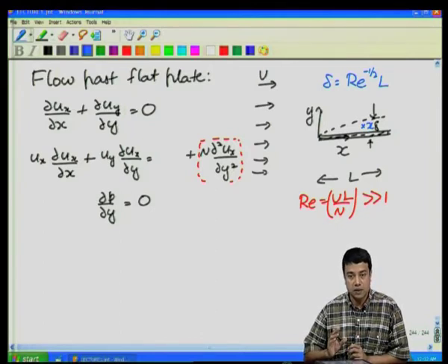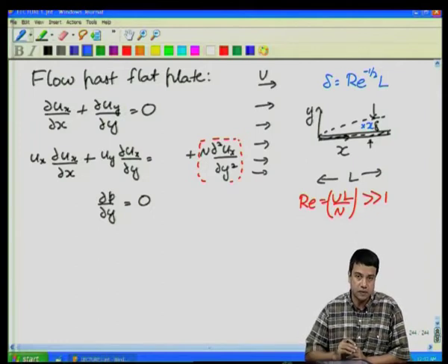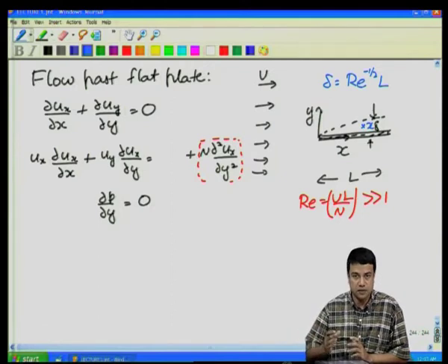It will only depend upon the distance to the upstream edge, because it is only downstream convection that is affecting the dynamics of the flow as well as perpendicular diffusion. Since L is no longer a relevant parameter, the flow is going to be the same regardless of whether the plate was length L, 2L or some other length, so long as it is larger than x, because what happens downstream does not affect the flow.